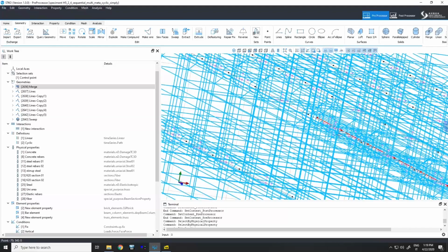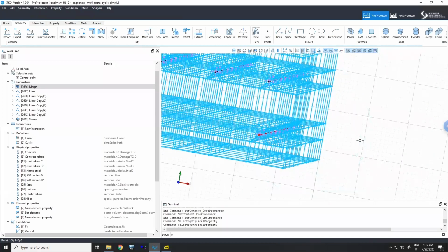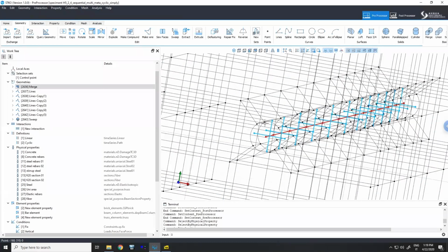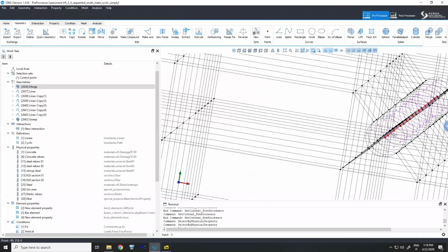And then you may say, okay, but why is it detached from the solid? Because in OpenSees, the solid has only 3 degrees of freedom per node, while the beam has 6 degrees of freedom per node. But OpenSees cannot handle 2 different elements that expect 2 different degrees of freedom sharing the same node. So basically, the node of the beam should not be the same as the node of the solid, okay? That's why we model it separately.